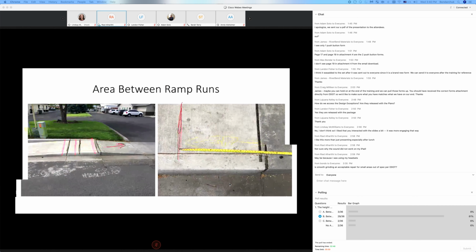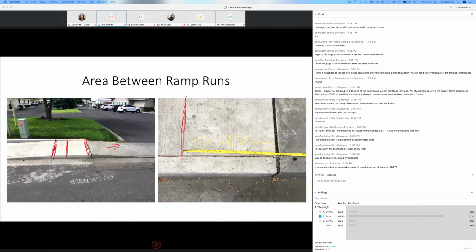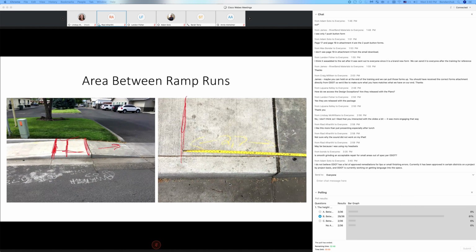I'm not sure why the ramp here should be right here. The distance should be measured from the top of the ramp if this is a flatter area. I would probably say if the ramp's not starting from here where I see the joint, if this is going this way, just make this one a flatter area, and that would fix the problem if it's more than 5 feet.